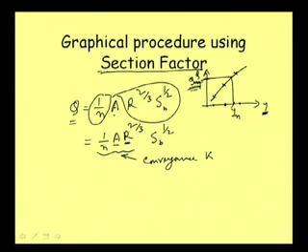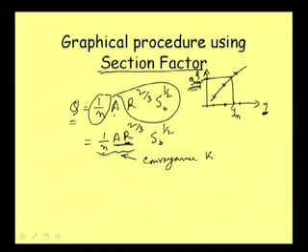So, these factors are basically related to the sectional size of the open channel, and then this n is not related to the size of the channel section, rather it is related to the roughness characteristic of the channel, and of course, some other parameters we discussed earlier that influence the n value, but definitely not the sectional size of the channel.